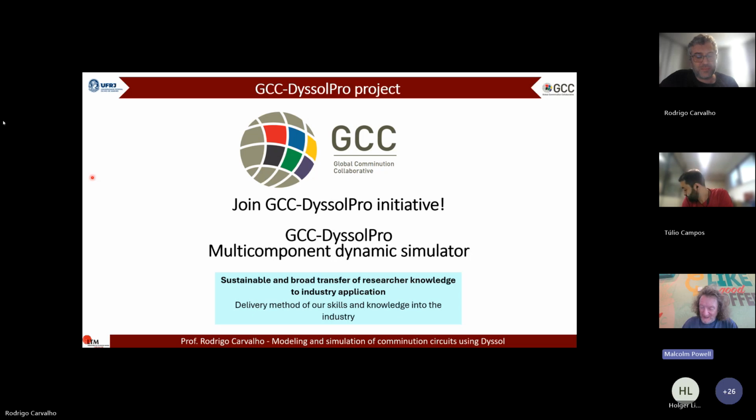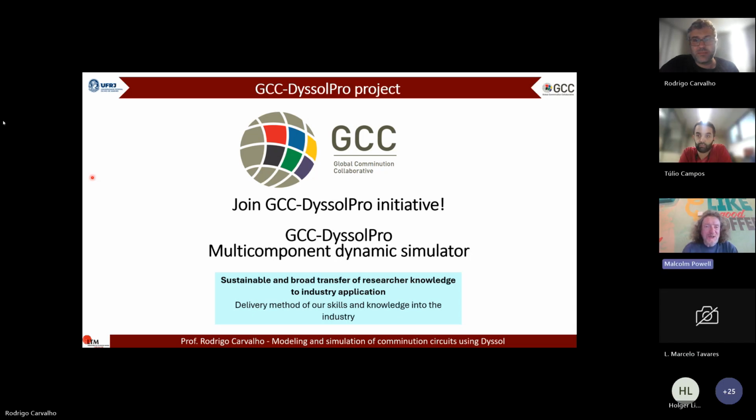Thanks, Rodrigo. Something I guess you didn't manage to get to is the process control system on top of the dynamics. It's very clearly my experience that you can go through a transient state you can't recover from. You can't get to what a steady state will predict, quite strongly in SAG mills, but you can go transient through an overload and you're done. Maybe you could express what could be the value of simulation, understanding those issues around the transients.